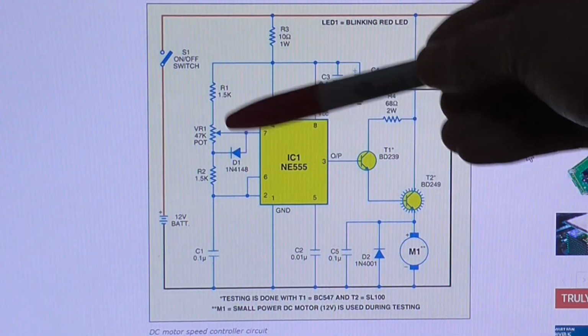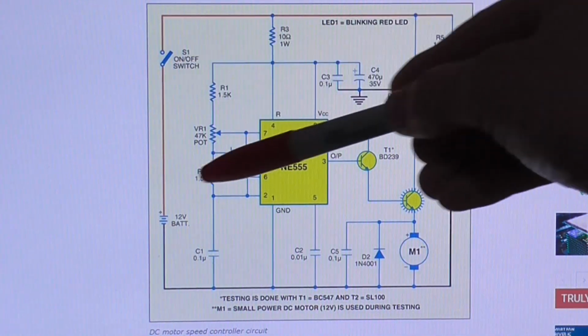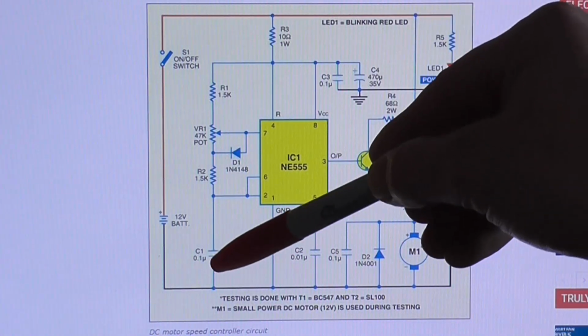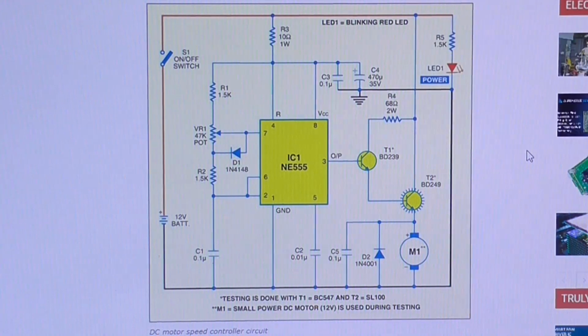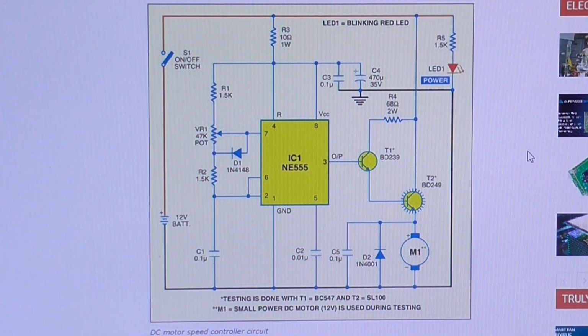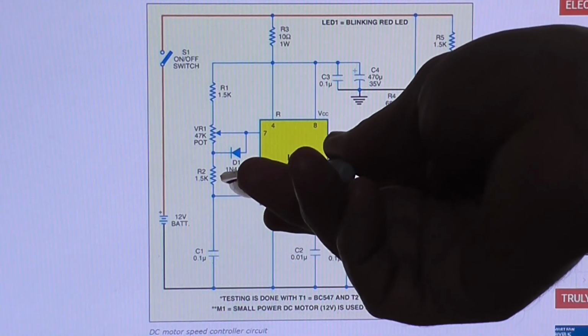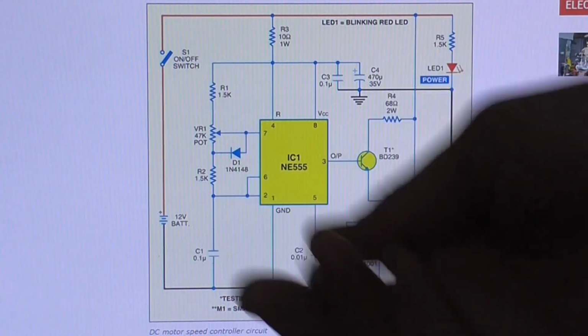So they're basically trying to ignore that through here and only have the positive supply going through to the capacitor, I think. Other than that, I'm not really sure what it's for. I don't have any 1N4148s, so I'm going to just use a 1N4004.